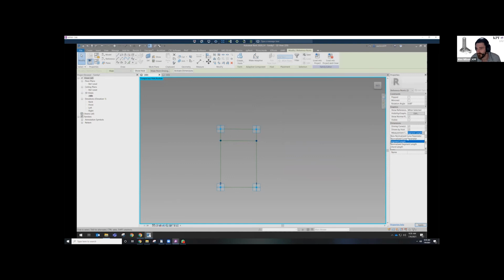Curve normal lengths are great if you do a lot of slanted panels, and I will show you why. Once I change it to normalized length, you can see it now becomes a fraction. The reason that is important is because as a panel starts to slant here, you can see that this is now no longer a meter. It's a meter on the right angled vertical line, but on the angled line, you're now starting to get into trigonometry. It's now no longer vertical. It's now no longer a meter. It's the angle, using those two distances to get that distance.